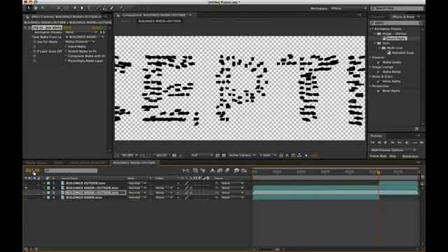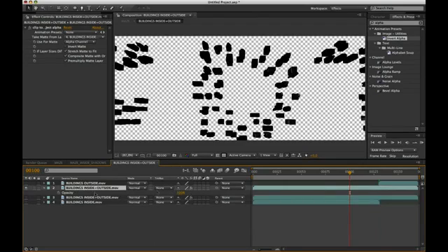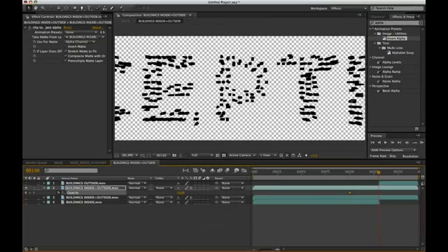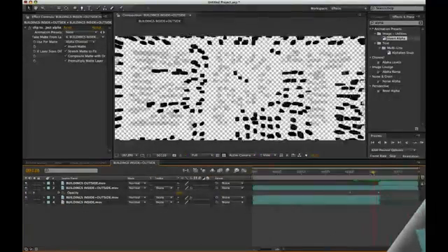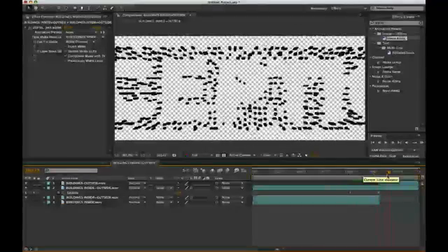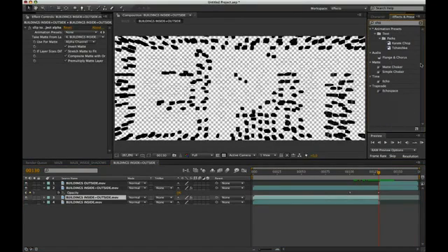Now go to 100 frame and set the value to 100. For the opacity interpolation of the inside part, fade out in the 130 frame to 0. If we want to clean up the alpha channel outside buildings, just apply the matte choker effect with value to 0.